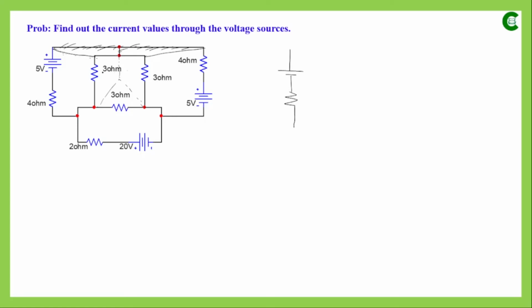These 2 points are the same, and we no longer have this resistor between them. There is no more component connected between them, so after drawing this branch, we can just connect these points. This point means the end point of this branch in the star connection. So we are joining them, and it will look like this.